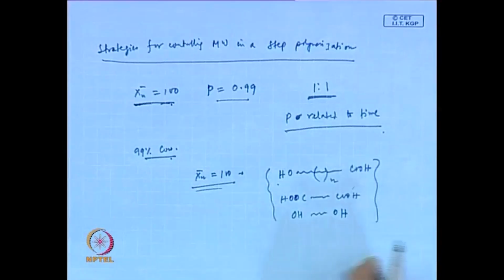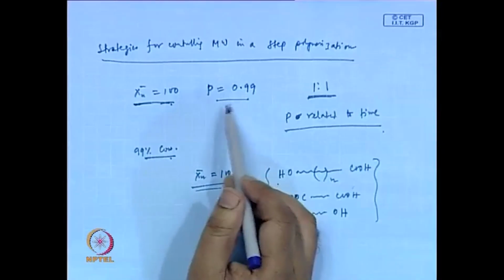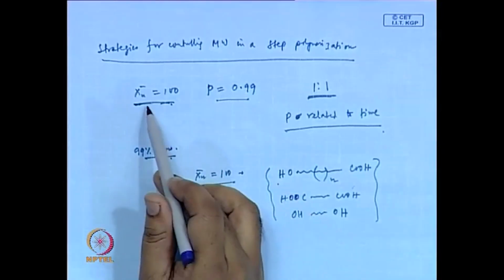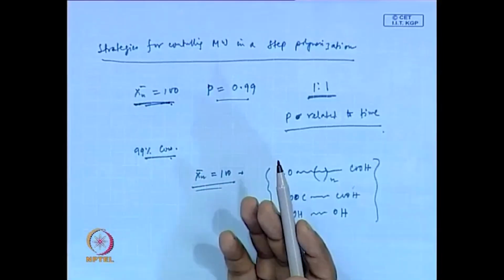These can react with each other or with the polymer backbone and degrade the polymer or build the molecular weight. So, at the end of your molding step, the molecular weight might be different from what you targeted, and your properties will be different. So, it is not advisable to stop the reaction in between at the level you targeted. So, how can we achieve that?